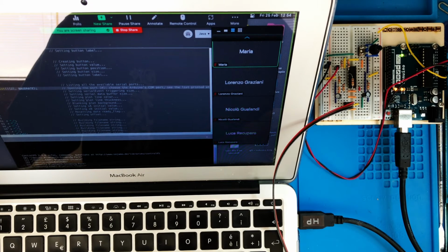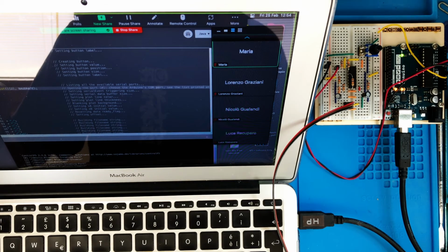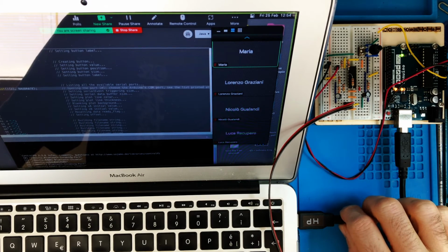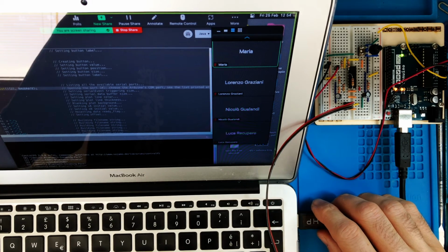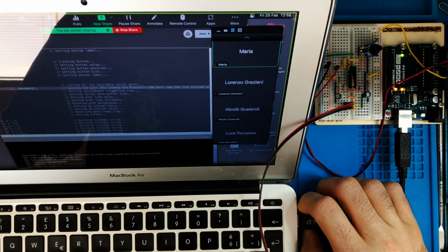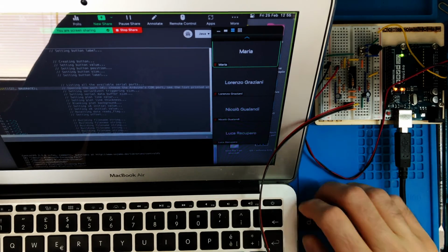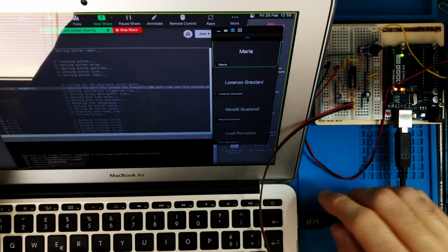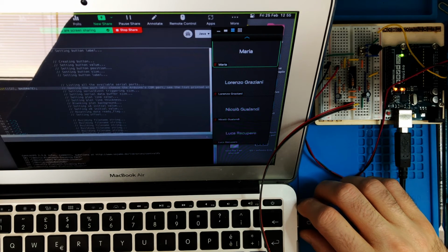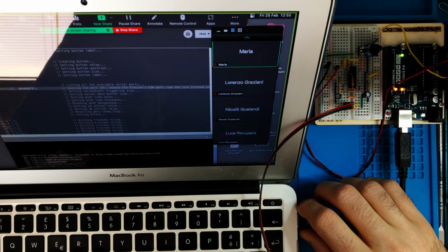So the thing that was confusing in the result of this display was that I was connecting the USB to the desktop computer, which is directly connected to the 220 volts 50 hertz mains, and so it was picking up some noise, this kind of slow sinusoidal that was overlapping everything, and the amplitude of that signal is much bigger than the one you have in the muscle.